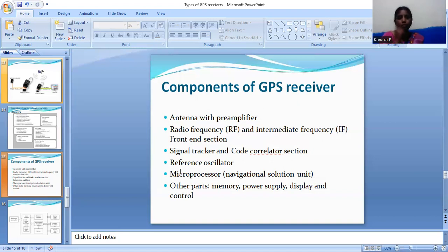So there's a schematic diagram: one end is the emitter, one end is the receiver. The emitter transmits the signal pulse, and the reflector is collecting the signals. A short but intensive pulse of radiation is transmitted to the reflector target, which is transmitted back to the receiver along a parallel path. The measured distance is got from the product of the velocity of the signal and the time taken to travel.